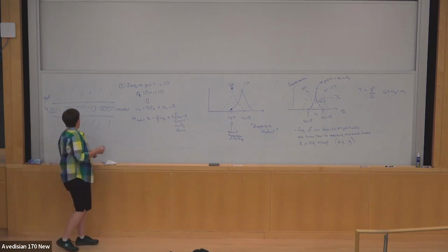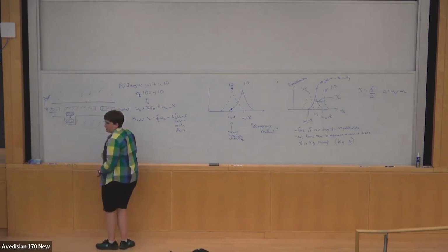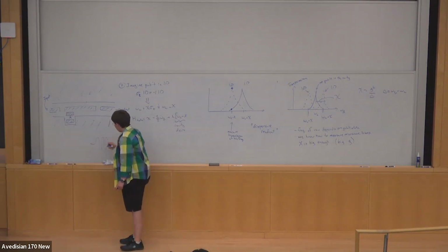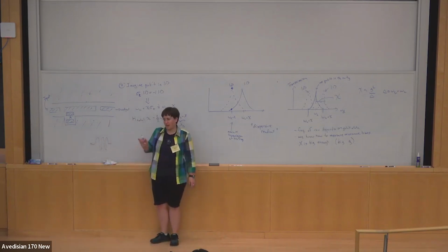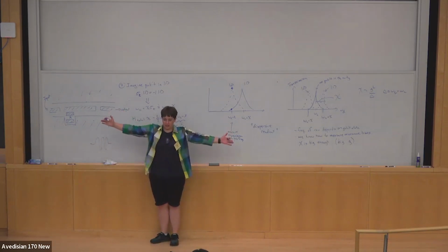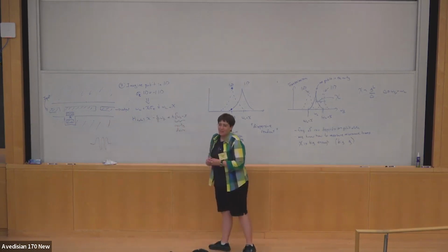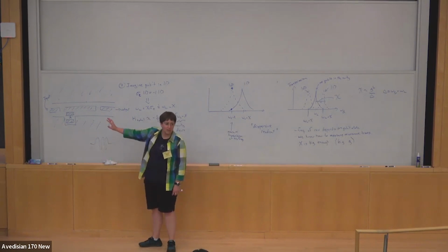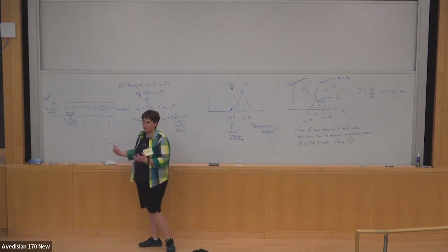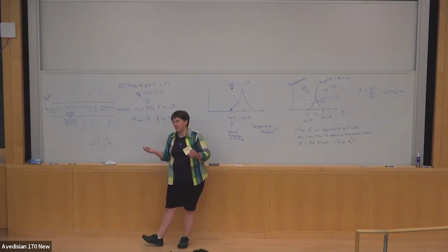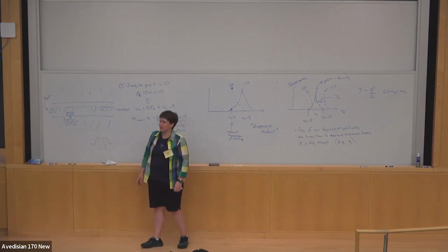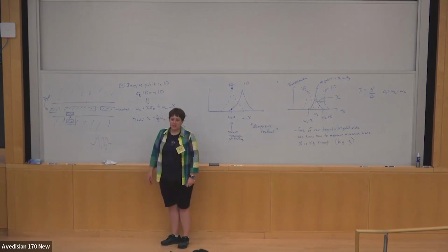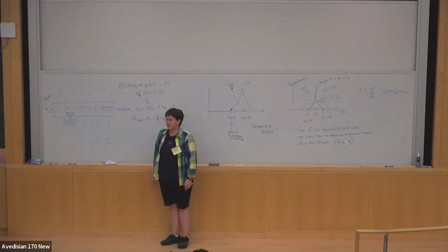There's a couple of tricks of the trade. One is that we never make a resonator in a straight line. We always tend to make them like this. Okay, this is somewhat helpful. It takes it from gigantic to huge. But there are also other ways to make a microwave resonator. This is one of the earliest and the most common, but there are much more compact ways to do it. Signal routing is sometimes a little more annoying. It's kind of a pick your poison sort of question. But it is a serious worry with this device footprint.